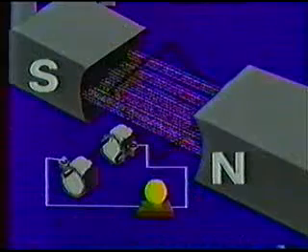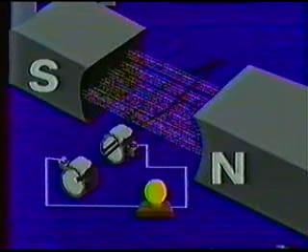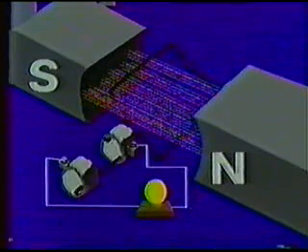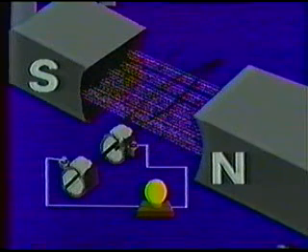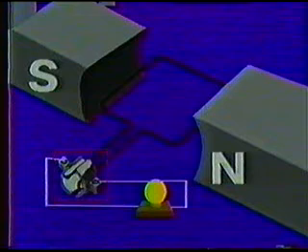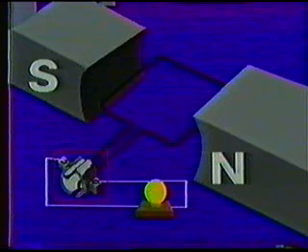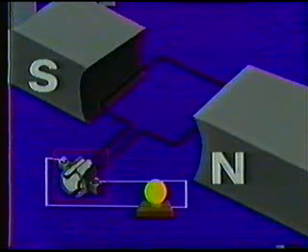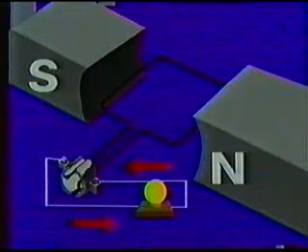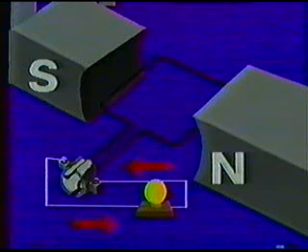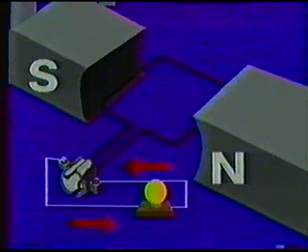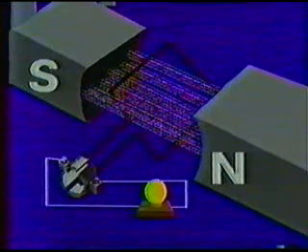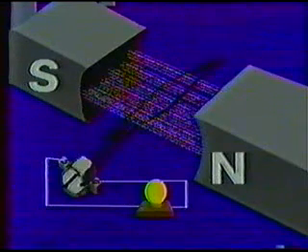But our discussion today is about DC generation, and as such, the voltage a device like this would produce is of little use. A device called a commutator is attached to the conductor ends. This device allows us to extract electricity while the voltage being produced is moving in the correct direction. Now we have a device that, if driven mechanically, would produce electricity.